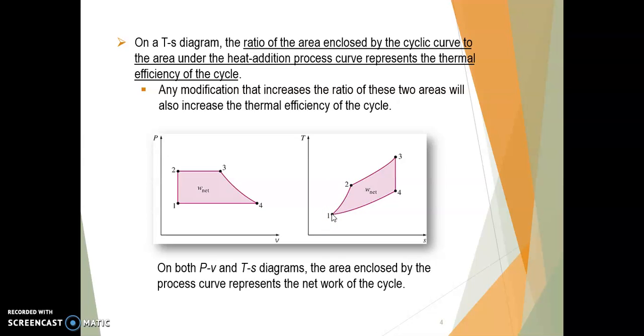the engine process flowing from point number one to point number two, where we are increasing the temperature slightly, then we move between two and three. At this part, some heat inlet is added to the system. Then we are reducing the temperature, but keeping the isentropy similar. Then we are rejecting the rest of the heat from the whole system. Then we get the W net based on the heat in minus the heat out.